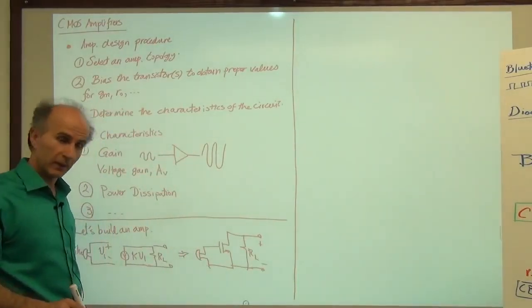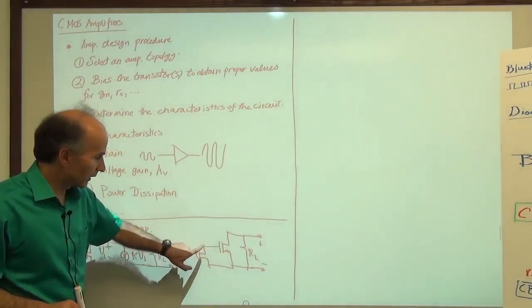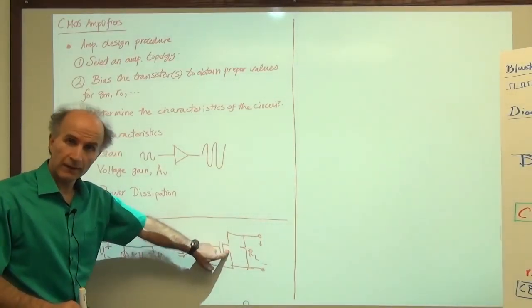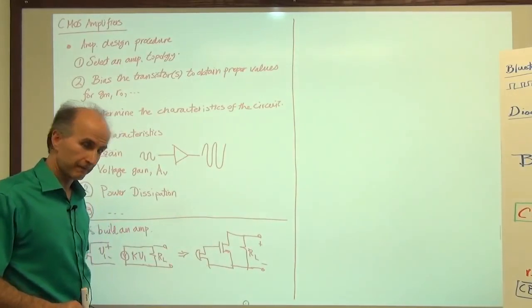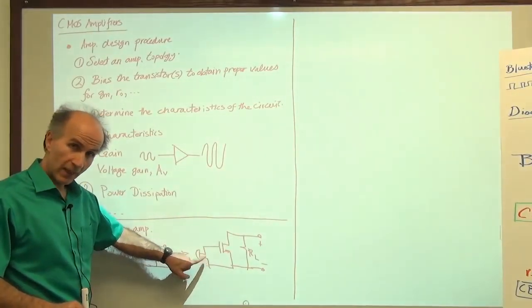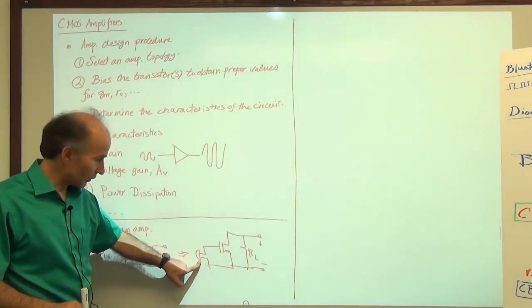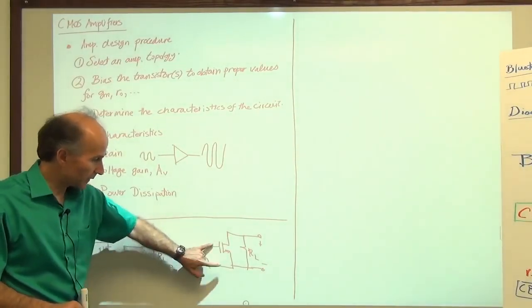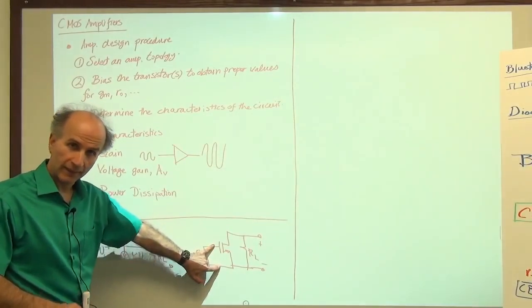Unfortunately, it wasn't, because in the absence of a signal, the gate source voltage is 0, the device is off, there's no amplification. I said, okay, well, why don't we place a voltage source, a battery, in series with this microphone to ensure that when there's no signal, we still have a respectable VGS.